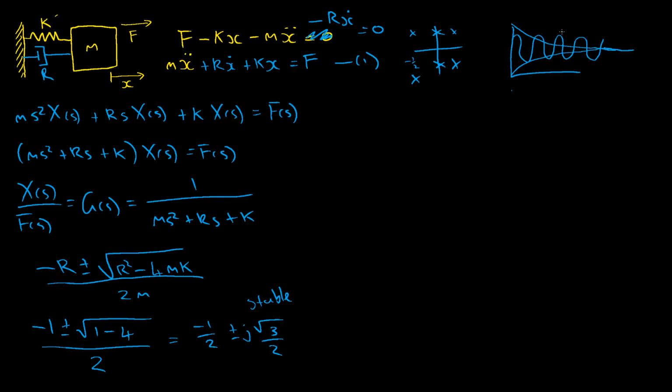It's important to carry on that distinction between marginally stable and actually stable. We say it's marginally stable when the real component is equal to 0. But how many things in the real world have you ever seen that are actually true 0? It might be 0.0001 or something like that, or even the slightest knock could transfer this function if there's noise or things like that.